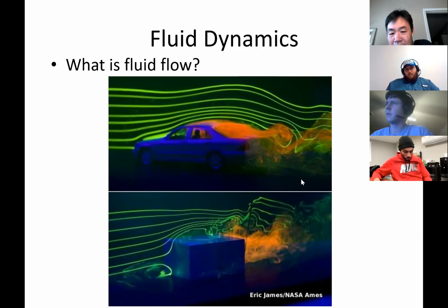It's not very clear, but you can still see the wake region behind the block, or I should say vortices. Actually, there are a lot of vortices in there. The wake for the block is bigger, and the circulation region behind the car is smaller. That's evidence showing the flow pattern is directly related to the force.